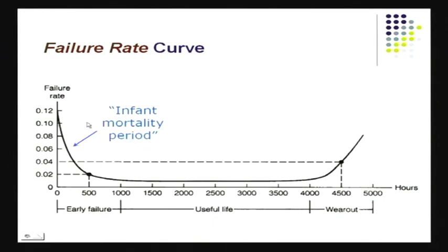And this is a small period of time. A few products die there, and these are generally because of manufacturing problems. Those sneak in, they get into the packaged stuff, and you end up with these products when you take them home. There is a cure for this, and that is done by doing burn-in before the product is shipped. So the failure rate is pretty high early on, and this is the infant mortality stage.